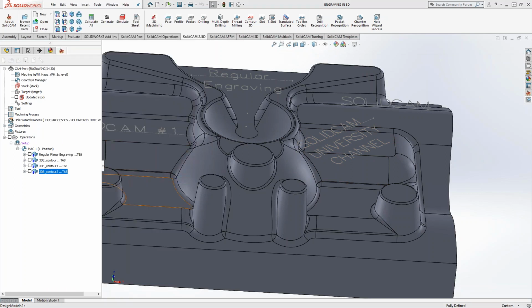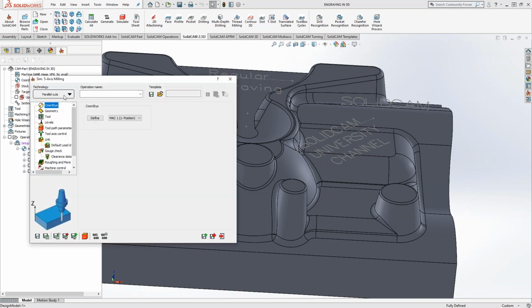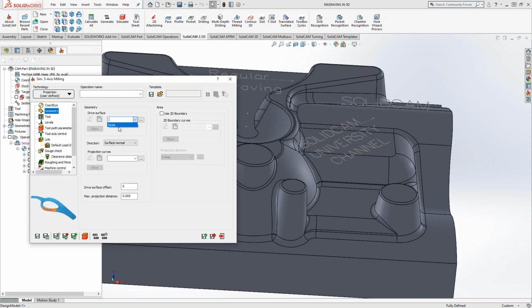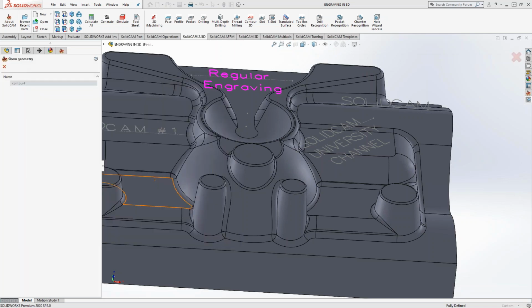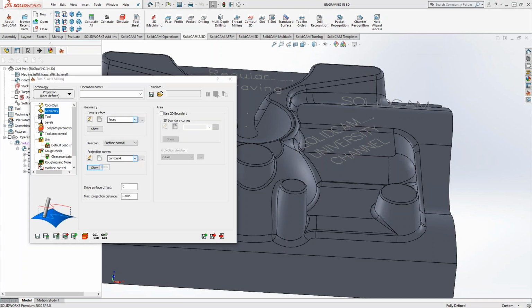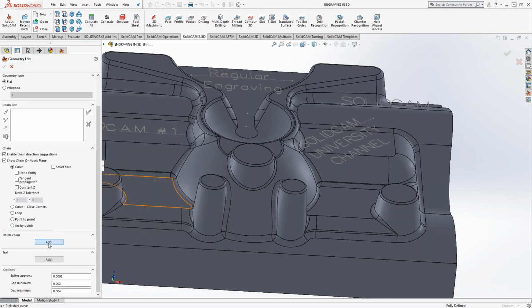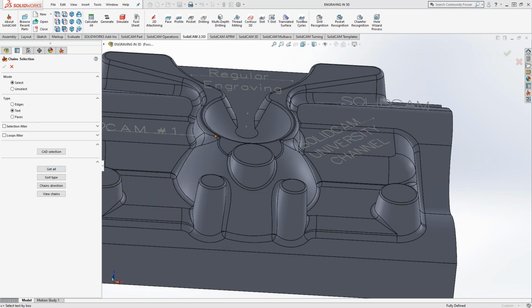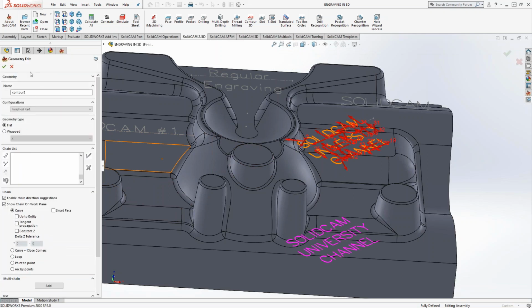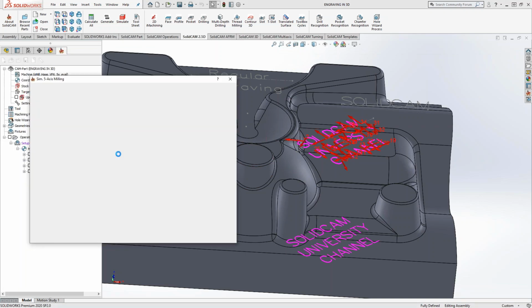Okay, let's go to simultaneous 5-axis, and we'll do exactly what we just did. Because remember that 5-axis simultaneous is still basically HSS. So we'll do user defined, geometry. Let's just use those same faces that we used before. So those guys right there. We'll project it. We'll choose, let's see, these should be the last ones I chose. Nope. Okay, we'll just reselect them. So multi-chain, because multi-chain is an option that exists anywhere you're choosing chain geometry. This is an option inside of this chain selection window, so you always have the same ability.